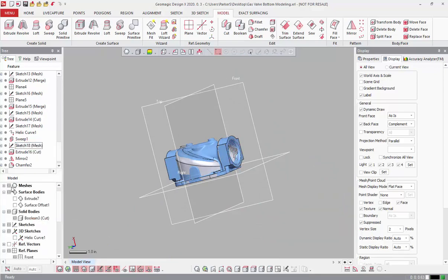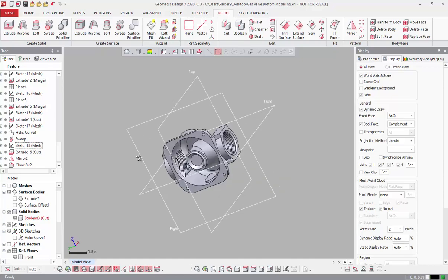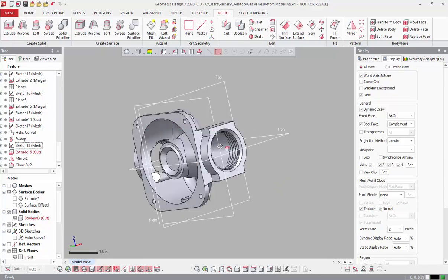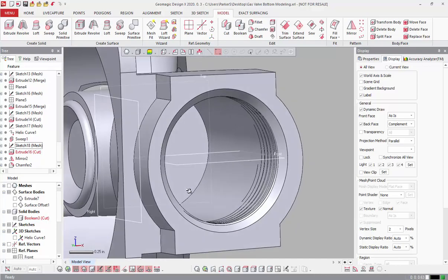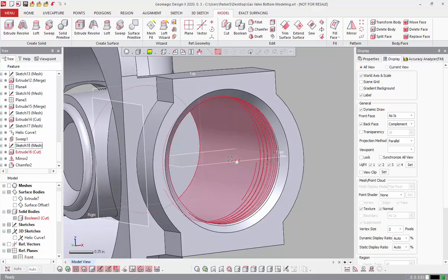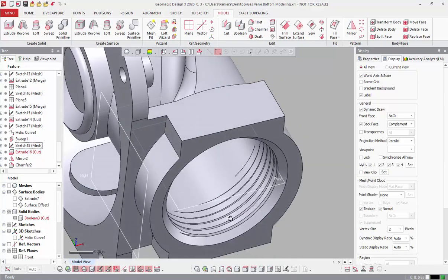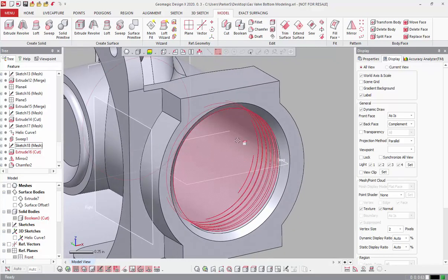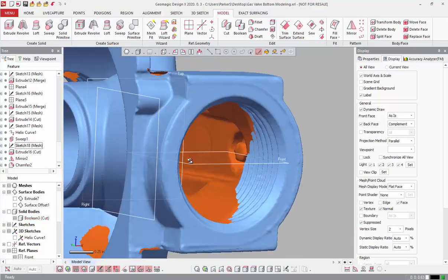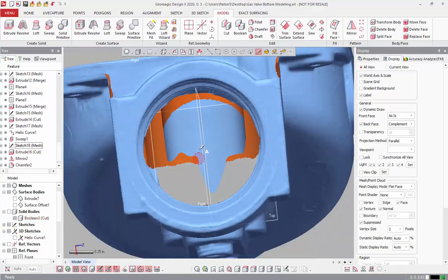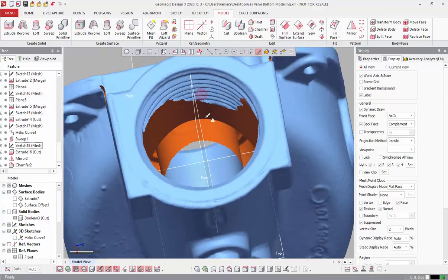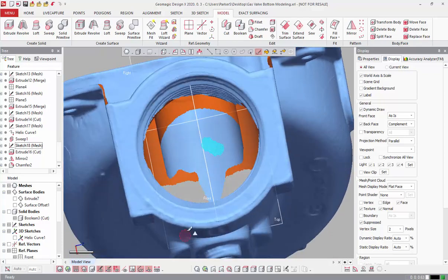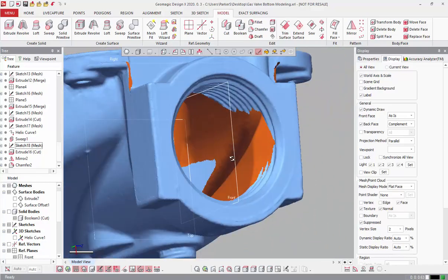All right, so we're almost done, right? We've got the threads in. In this case, a little bit different because A, I didn't taper that extrusion, so I probably need to check that out. And B, since this is a little bit different of a feature here, it may be something where I'd want to punch a slightly larger diameter bore out so that these threads progress into the part. Again, tough to tell without actually looking at the model because all I see here are threads, but I know that this is not all thread all the way out to this surface. So I need to make some design decisions on how that's supposed to look.